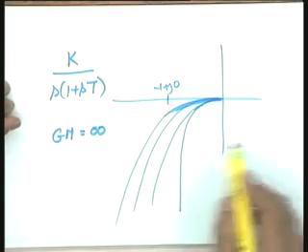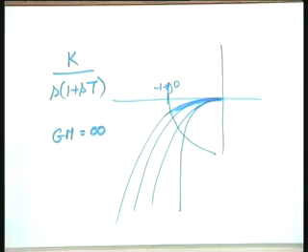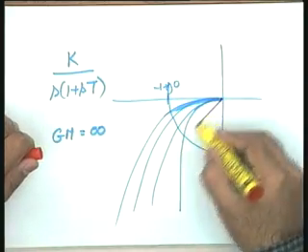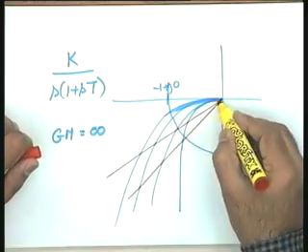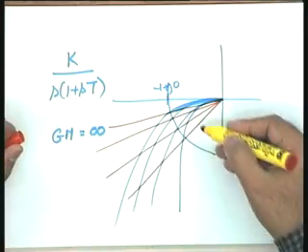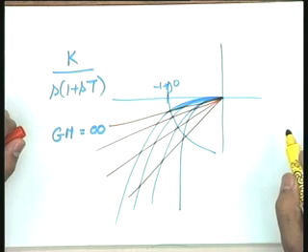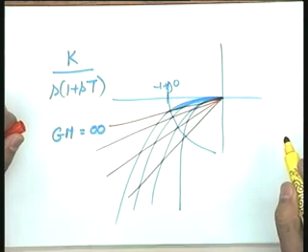So your gain margin is infinity in this particular case, and the phase margin you can see will depend upon the value of k. So, this much is the phase margin here. The phase margin is reducing, phase margin has further reduced as you keep on increasing the value of k, while in every case your gain margin is equal to infinity.